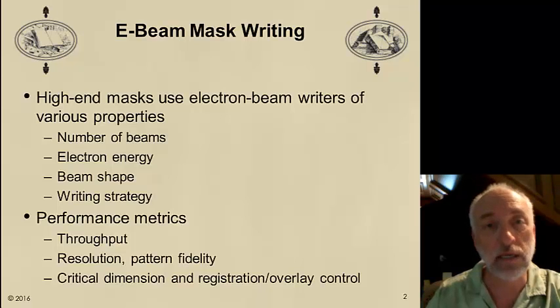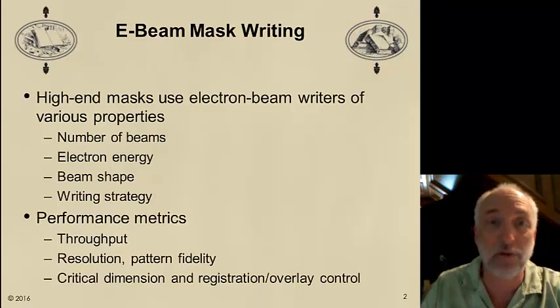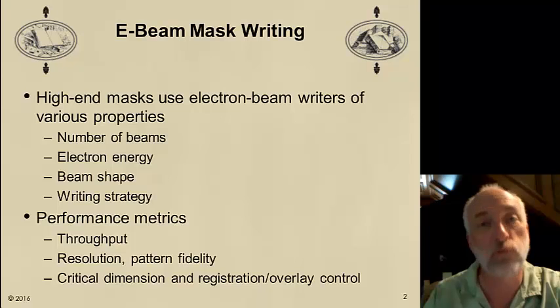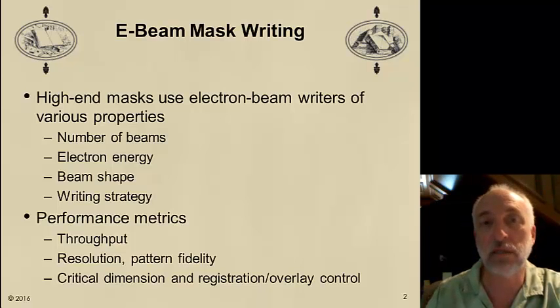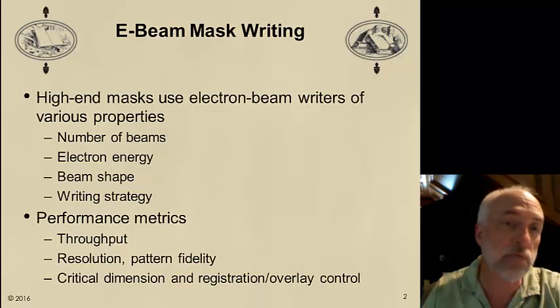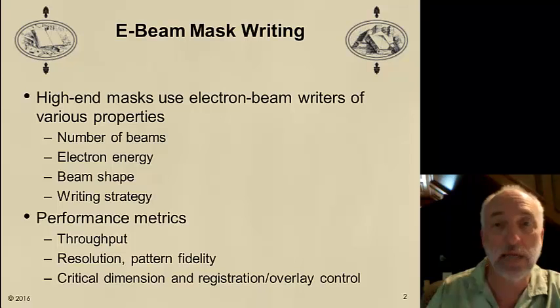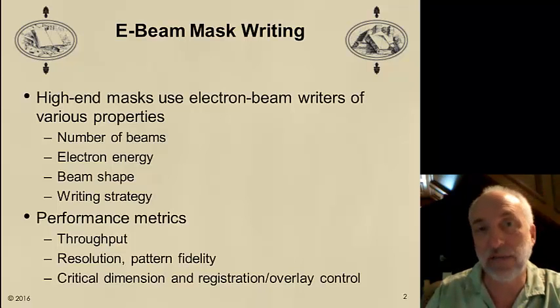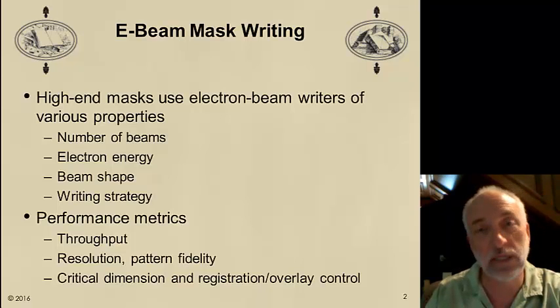Now, the key to the lithography process used in making masks is that we don't have a mask to start with, right? We have to use direct write lithography. And e-beam lithography is the direct write lithography of choice for high-end mask making today because of the resolution. Now, there are many different kinds of e-beam mask writers with different properties.